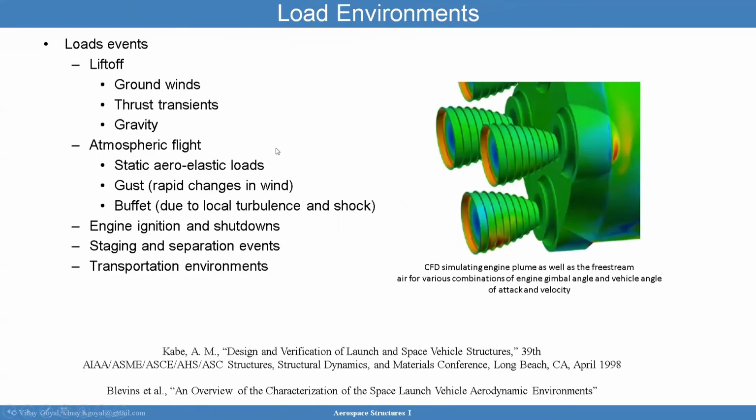There are several load environments of high importance. We have the liftoff events, and liftoff includes ground winds, which I'll be talking about a little bit later, thrust transients, gravity, atmospheric flight, static aeroelastic loads, gust, which really involves rapid changes in wind, buffet loads due to local turbulence and shock, engine ignition and shutdowns, staging and separation events, and the transportation environment. So all these load events have to be considered in the design.